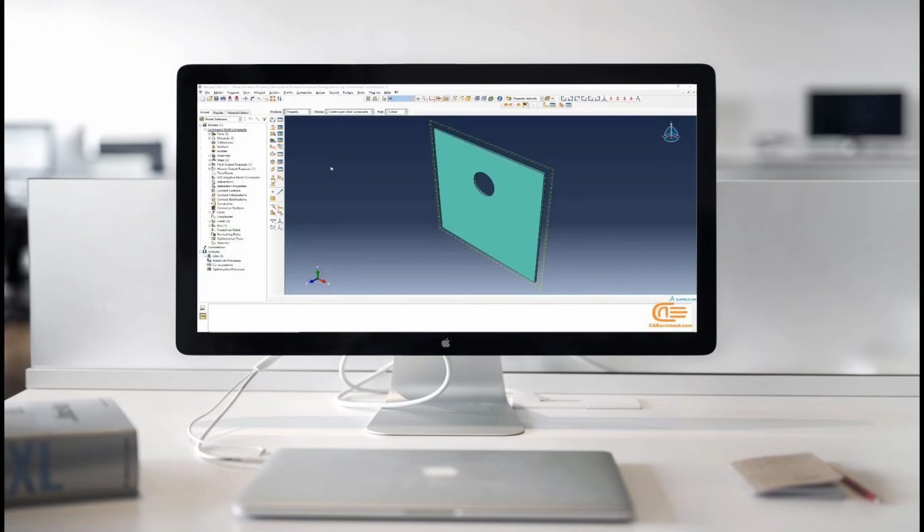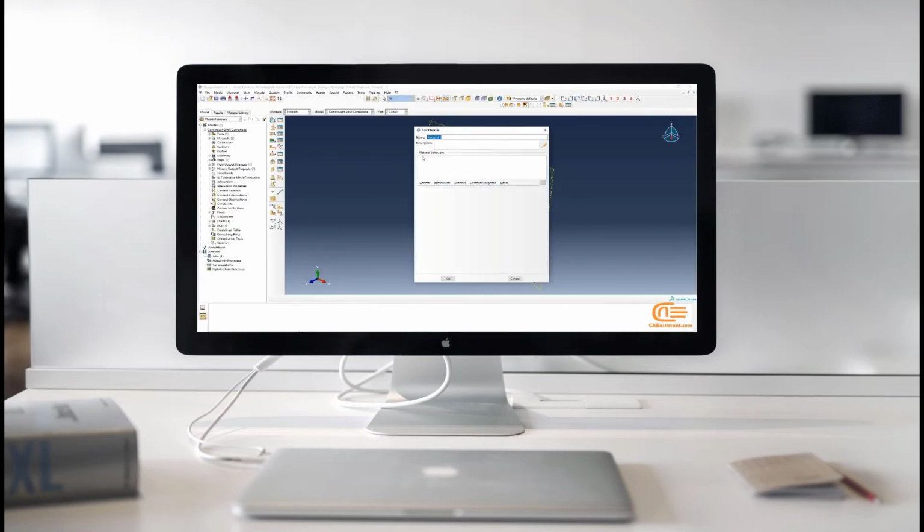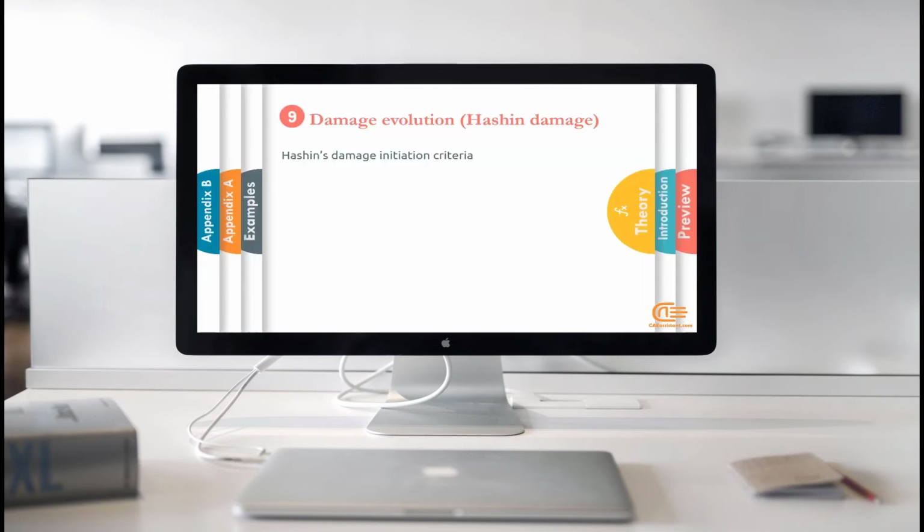Azzi-Tsai-Hill theory. The Azzi-Tsai-Hill failure theory is the same as the Tsai-Hill theory, except that the absolute value of the cross-product term is taken. This criterion is defined in 4 modes for tension and compression in the matrix and fiber. The equations of the 4 modes are these, as you can see.